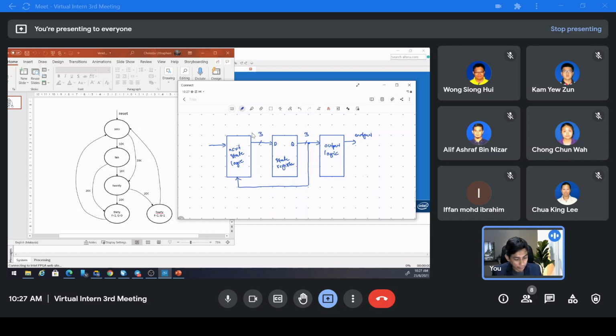If our circuit, this is FSM, this is Moore FSM. All right. What is the difference in terms of circuit? Yeah, Moore and Mealy. So the difference is that for Mealy, you have another connection to here. The input here also drives the output logic. That is Mealy type FSM. But for Moore FSM, you don't have this. So this is Moore. All right. So this is the general form of the finite state machine.